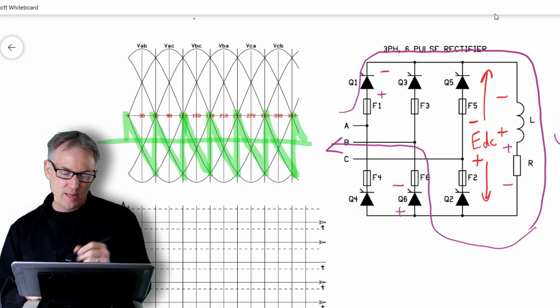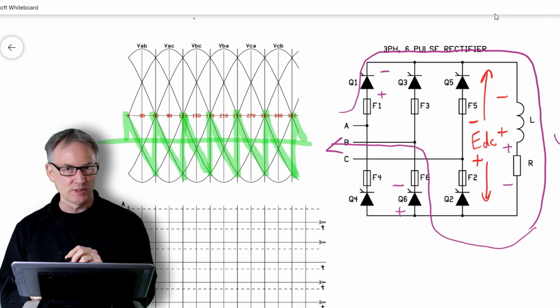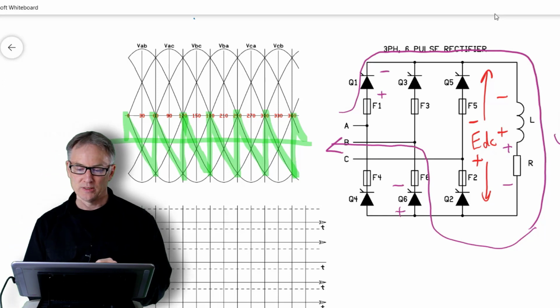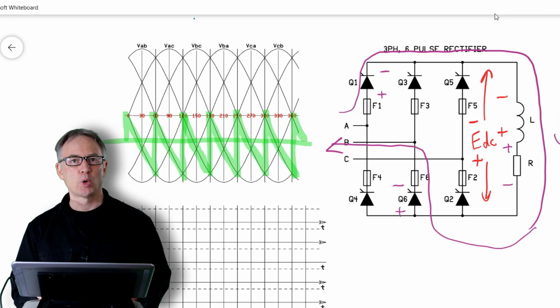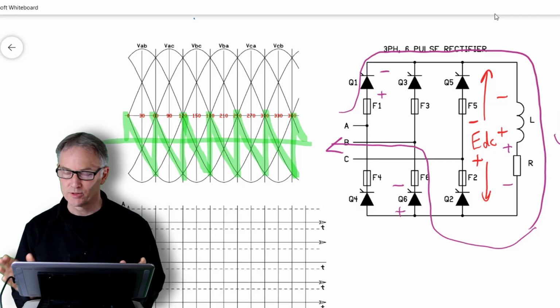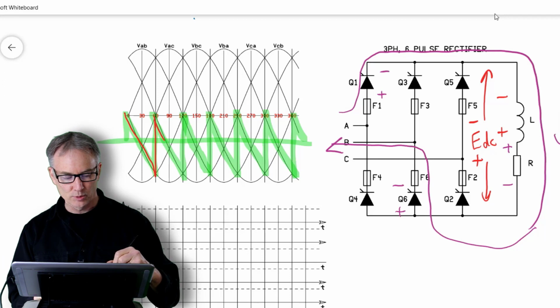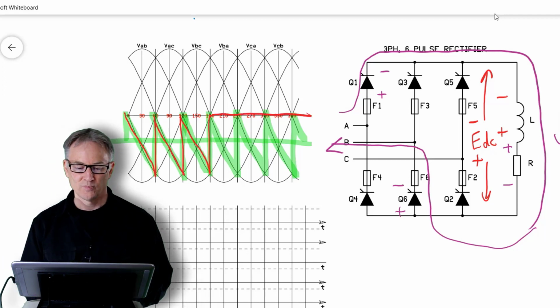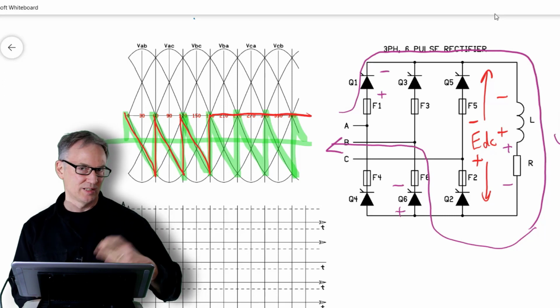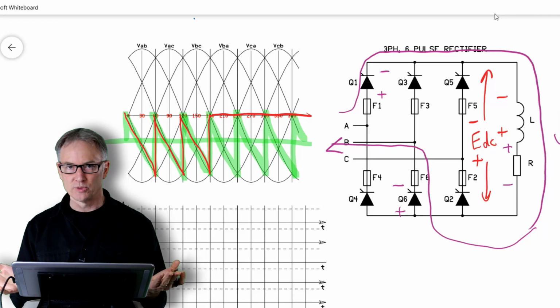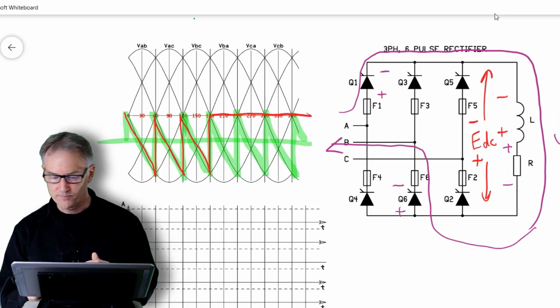So collapsing inductive energy is the only thing that's keeping this going. Once the current through the inductor collapses below the minimum hold level of the SCRs, then the SCRs are just going to shut off. And at some point you would see the voltage waveform kind of doing this, and then at some point it'll just go to 0. Okay? So even if you maintain the gating past 90 degrees, you're just going to end up with 0 current at some point in time.